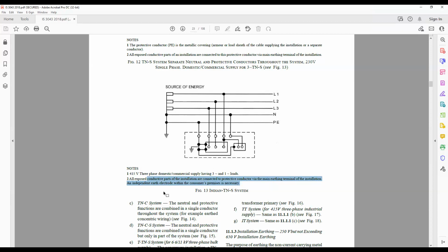But the problem is, for industrial and commercial premises, most of the installations or a large number of buildings in India are following, for example, neutral two copper plates and body two GI pipes. For the main panel, two more GI pipes. For lift, two more, UPS two more. Those are never written in the standard, and those things are removed; very clear clarity is given. As a result, such mistakes cannot happen in future.